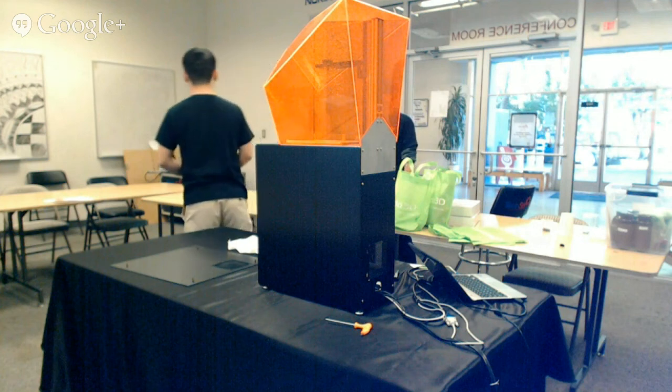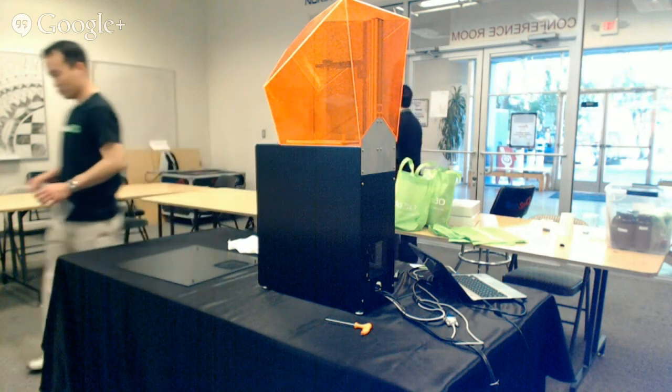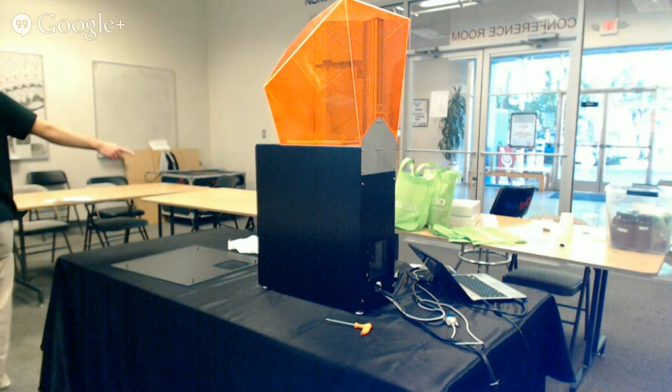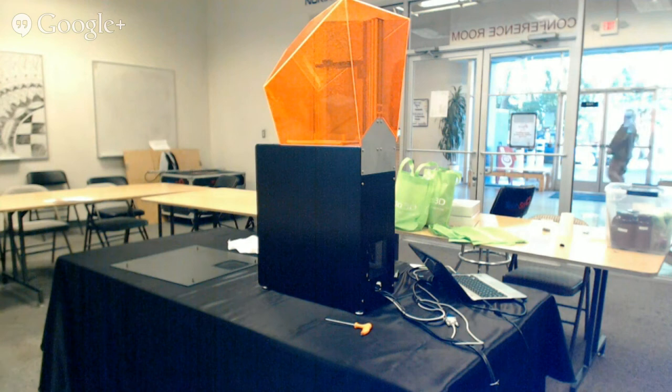Imagine a vat that's as big as this table is going to cause this bow in the top surface. And so there's a wiper system designed to smooth that down, to break the surface tension. And the chemistry of that resin is a little bit different too. The chemistry of the resin is what would primarily control cure depth, because now you're shooting down into the liquid. The laser could go an unlimited depth unless the resin itself was inhibiting the cure.